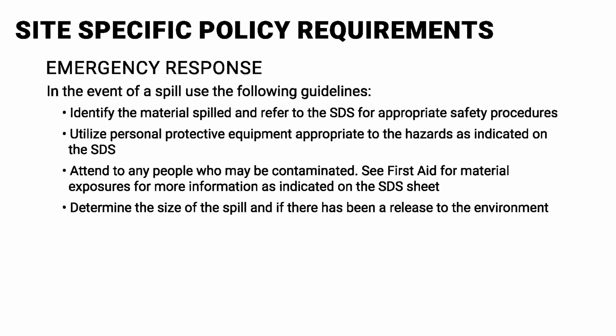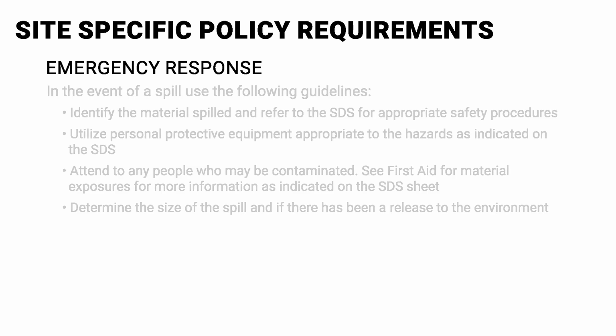Emergency response. In the event of a spill, use the following guidelines. Identify the material spilled and refer to the SDS for appropriate safety procedures. Utilize personal protective equipment appropriate to the hazards as indicated on the SDS. Attend to any people who may be contaminated. See first aid for material exposures for more information as indicated on the SDS sheet. Determine the size of the spill and if there has been a release to the environment.